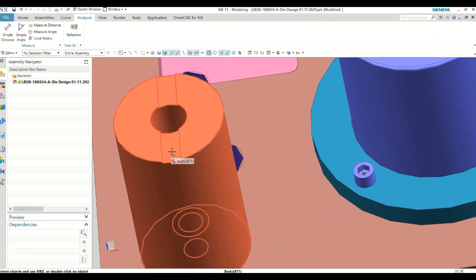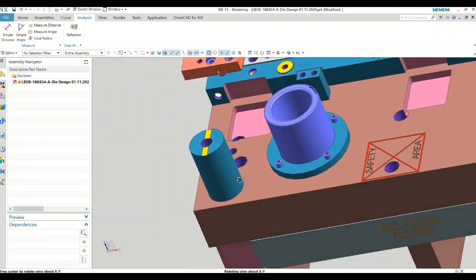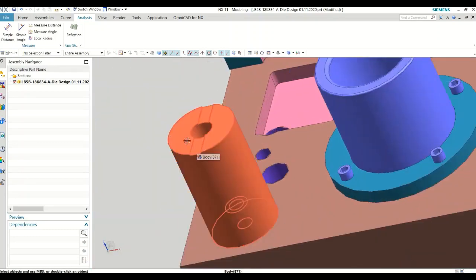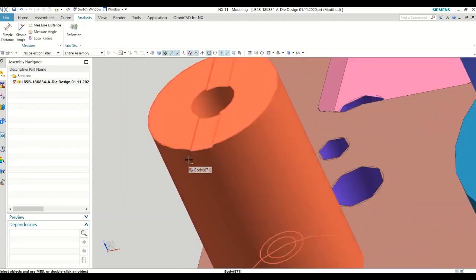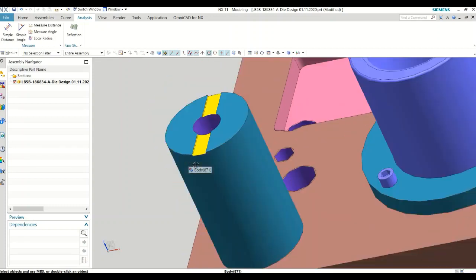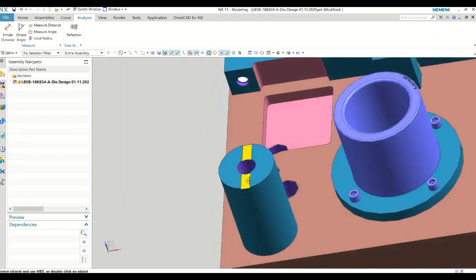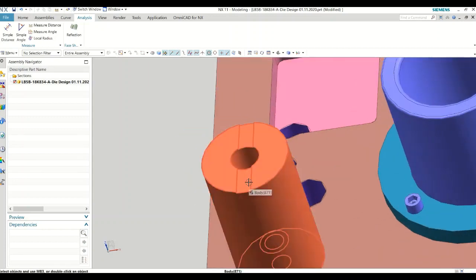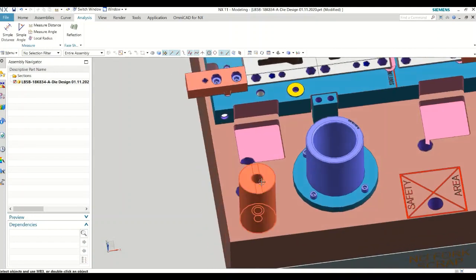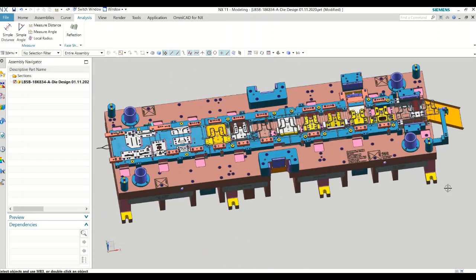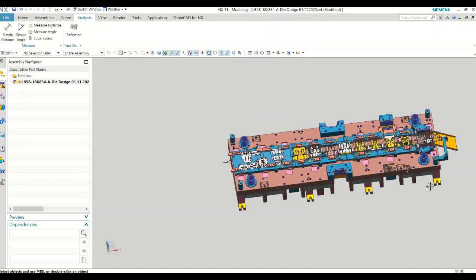That's 0.05 inch. We say 50 thou. It's the inch standard in the USA at the customer end. Even if they have metric, we maintain 50 thou. So this is 1.27 millimeter deep. What happens? We have a very soft aluminum wire. We keep it here. When the upper die comes, it hits.